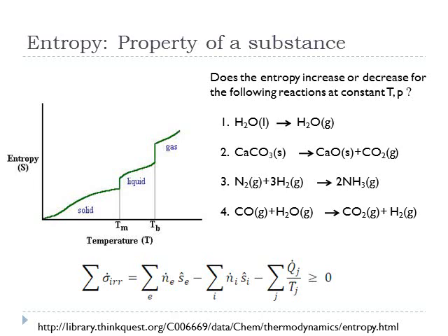So what we can say is that the flow of entropy exiting the system minus the flow of entropy entering the system minus the flow of thermal energy divided by the temperature that it enters or exits has to be greater than 0. So as we go from liquid water to gaseous water, the net of these terms is going to be positive.